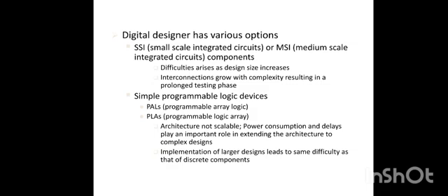Digital designers have various options, that means small scale integrated circuits, that is SSI, or medium scale integrated circuits, that is MSI. Difficulties arise as design size increases, so interconnections grow with the complexity, resulting in a prolonged testing phase. So we use PALs and PLAs. That means the next step is simple programmable logic devices. PAL means programmable array logic and PLA means programmable logic array.